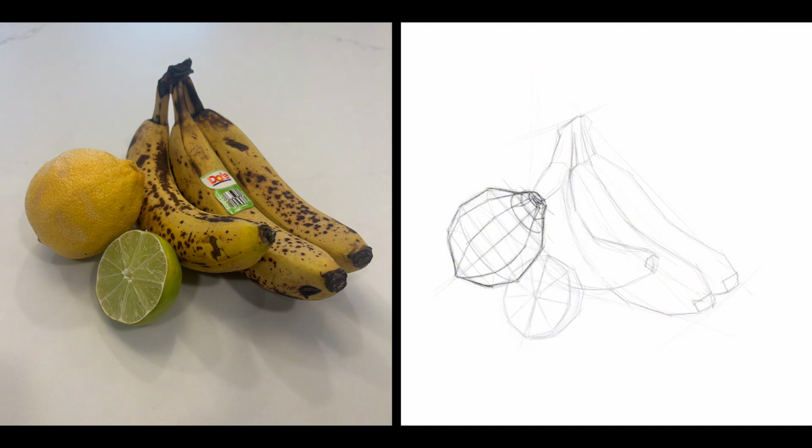Step 6. Interior planes. Now begin describing interior planes. Imagine carving the object from a block of wood. Use segmented lines that run along the longitudinal axis to mark major planar edges. These divisions create the illusion of top, side, and angled surfaces. Each form should be divided into 3 or 4 major planes. At this stage, your drawing might resemble a globe with latitude and longitude lines. Use light and shadow to help locate natural breaks between surfaces.